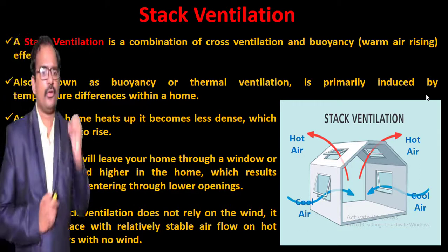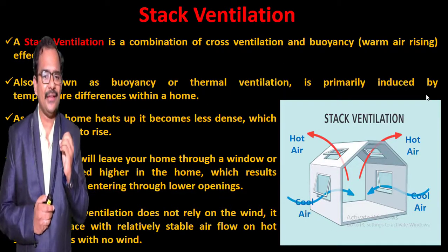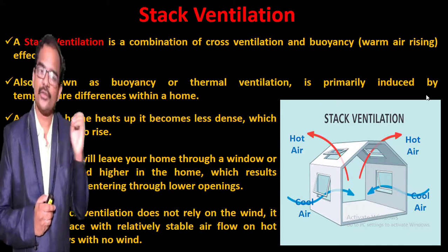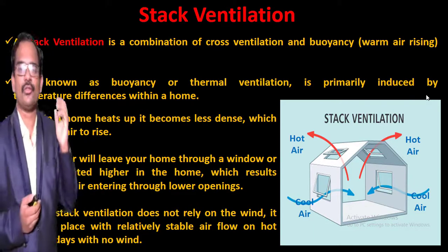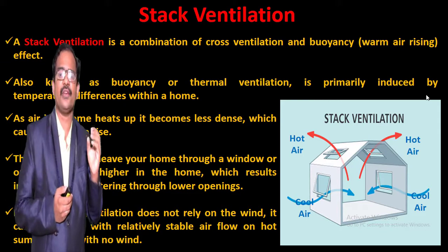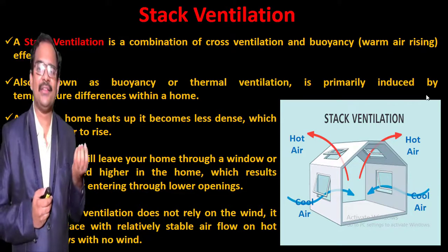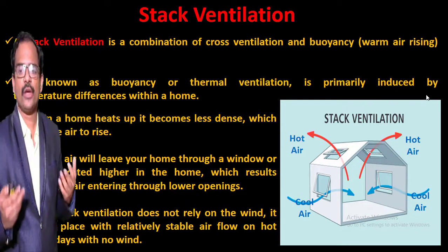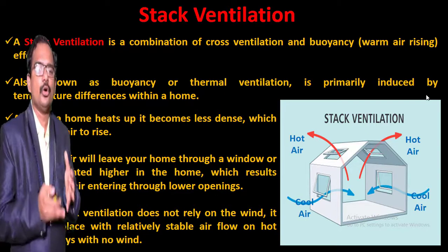So because stack ventilation does not rely on wind, it can take place with relatively stable airflow on hot summer days with no wind. So no wind is required. It's because of the pressure difference and temperature difference. It's because of the temperature difference that the air circulation will happen inside this stack ventilation unit. And even when you have no wind, the system will work and provide ventilation to your home.